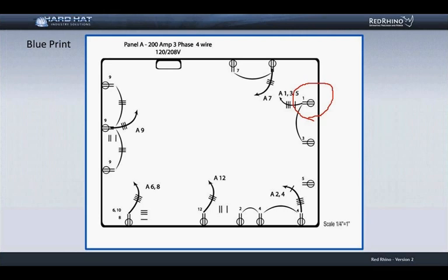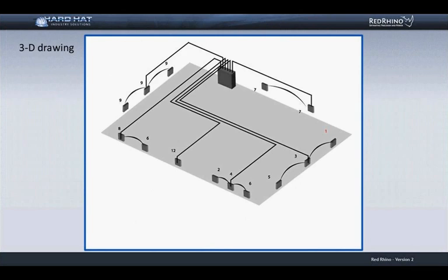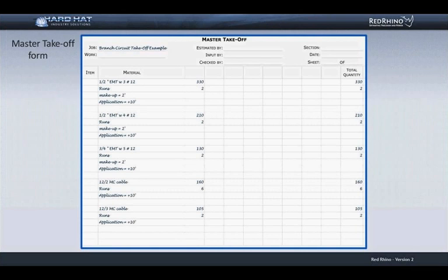Next, I measure the MC cable. Let's say the conduit feeding from outlet to outlet on the drawings is MC cable. I roll it off the same as EMT conduit. I roll off all the 12-2 MC cable, then the 12-3 and 12-4 and so on. I write down the total run length on the material takeoff sheet as well, showing the number of runs in application. I will not demonstrate taking off the MC cable, but show you the results on the takeoff sheet here.